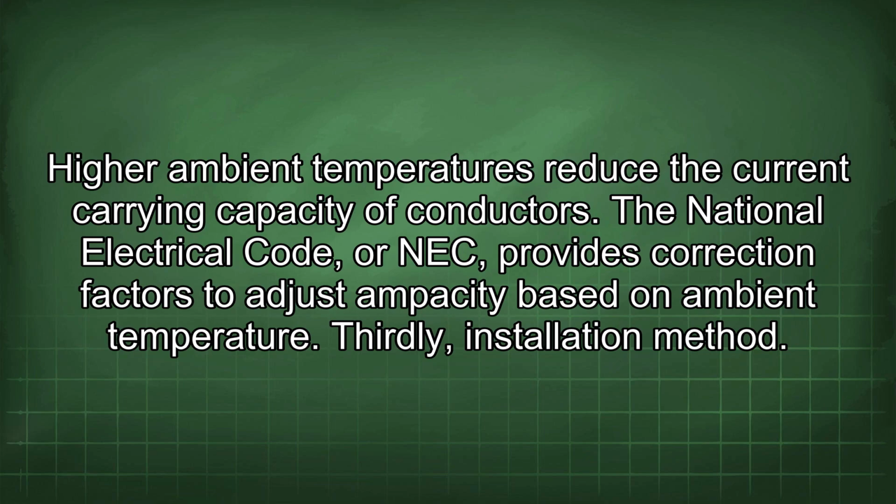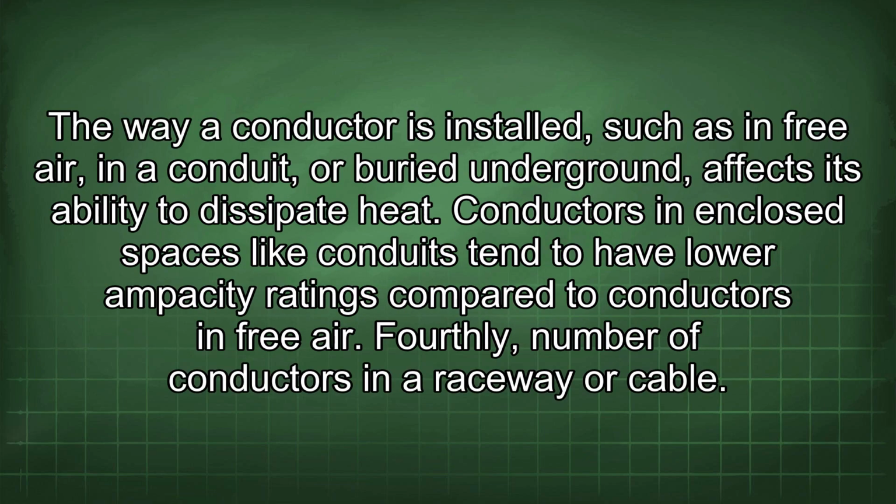Higher ambient temperatures reduce the current carrying capacity of conductors. The National Electrical Code, or NEC, provides correction factors to adjust ampacity based on ambient temperature. Thirdly, installation method. The way a conductor is installed, such as in free air, in a conduit, or buried underground, affects its ability to dissipate heat. Conductors in enclosed spaces like conduits tend to have lower ampacity ratings compared to conductors in free air.